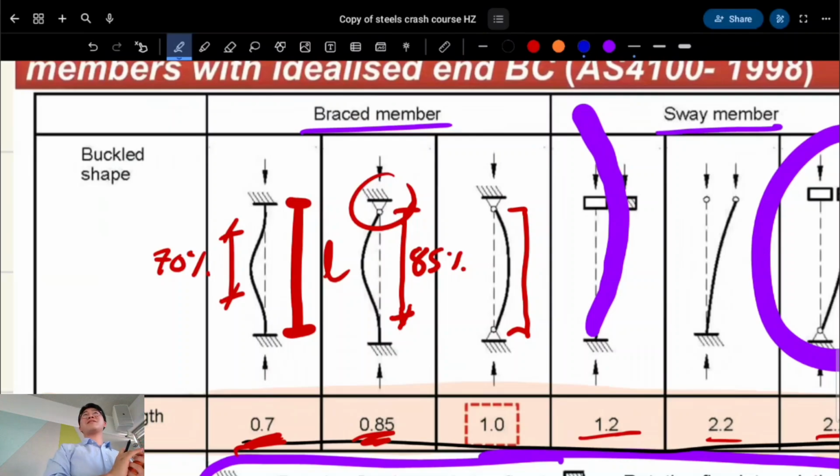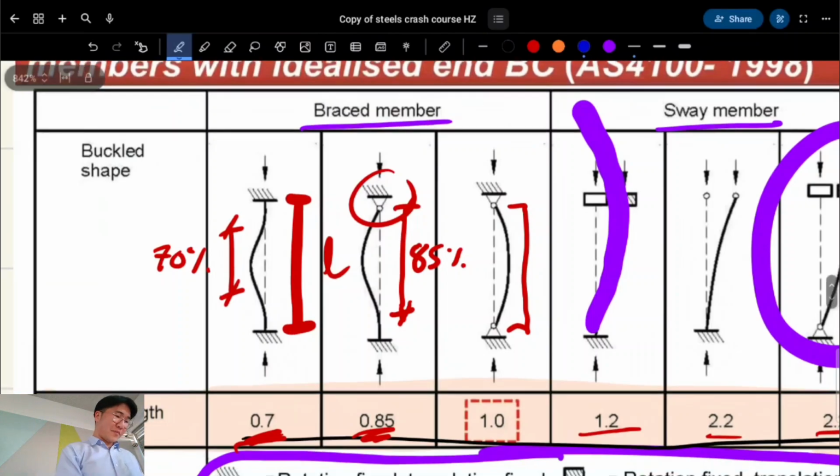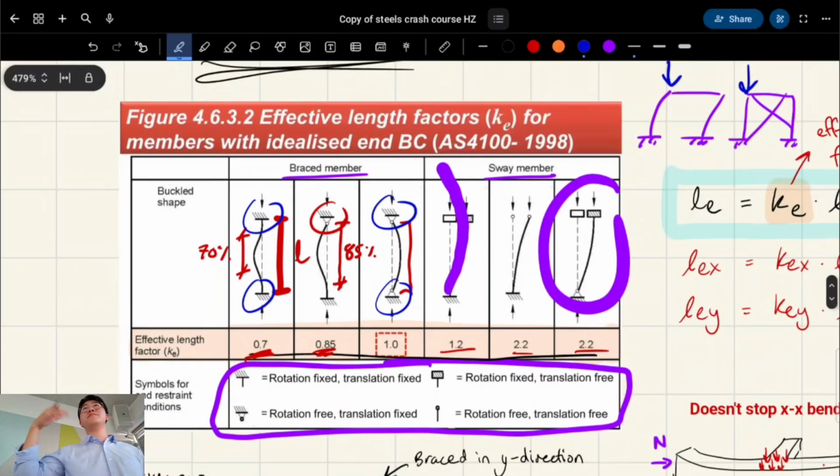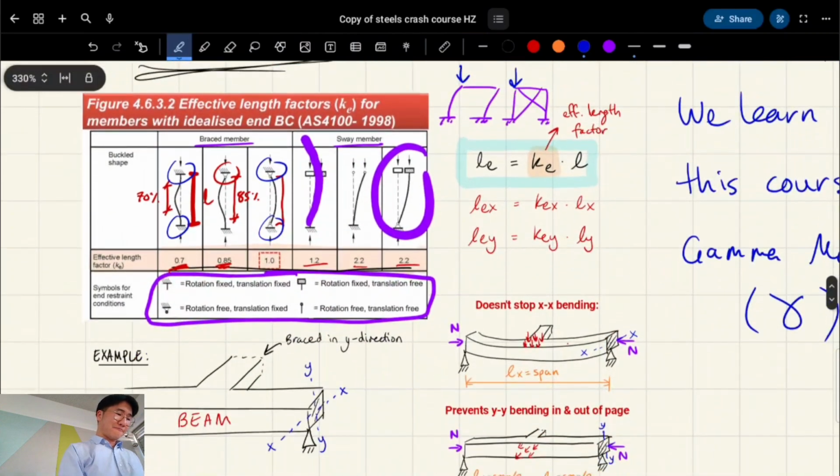You're 1.85. Yeah, that's perfect. That's basically what we use. Yeah. So not because it's exactly like this apparatus, it's because it's somewhere in between being rigid and pinned. Because it really is based on how thick the columns are and so on. Anyway, sorry, that was a bit of a tangent. But I hope that gets you thinking a little bit about how important the K factor is for buckling and everything to do with column design.